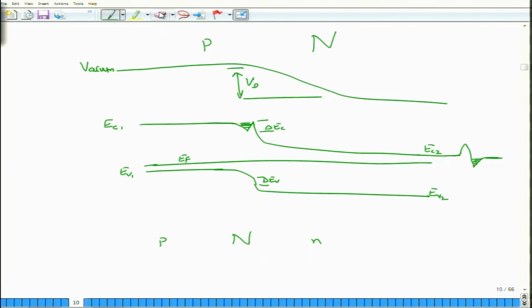Eventually the region here on the N type material would actually have the same value of EC. So, we will call this EC3. This one would simply drop, have a sudden transition and then move back to EV3. Okay. The Fermi level, of course, I did not write it correctly, but the Fermi level has to be constant. Okay. So, I should have written down the Fermi level and then made these bends as such.